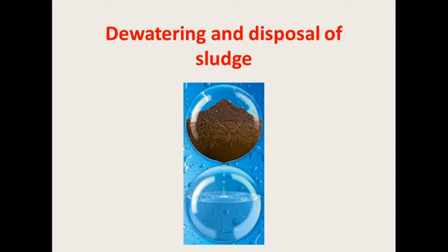We also covered that anaerobic digestion is nothing but the biological degradation of organic matter performed in the biodigester. During this process, much of the organic matter is converted into biogas, that is methane and carbon dioxide, and the process can reduce the organic matter content of sludge by 40 to 50%. So as we know, the anaerobic sludge digester consists of biogas at the top, then liquid, then sludge, and finally the mixing zone. These are the various parts of the anaerobic sludge digester.